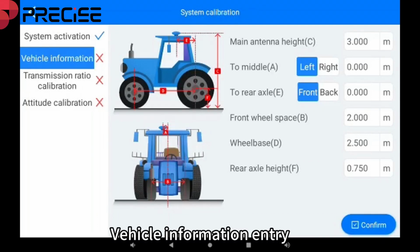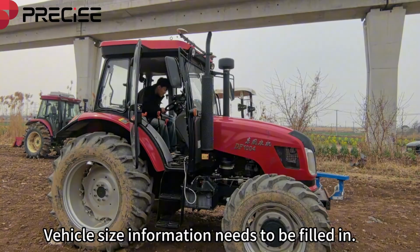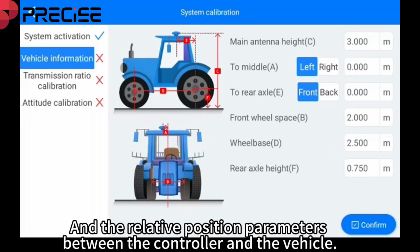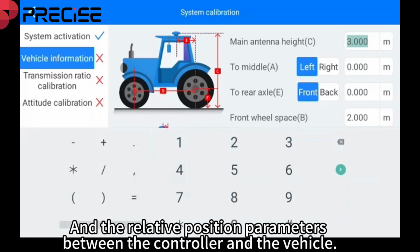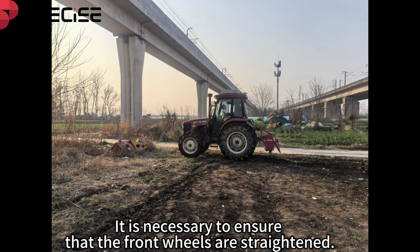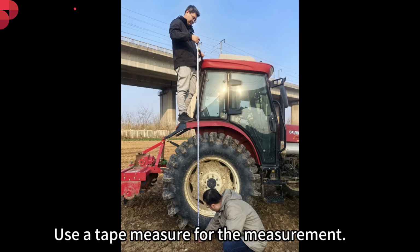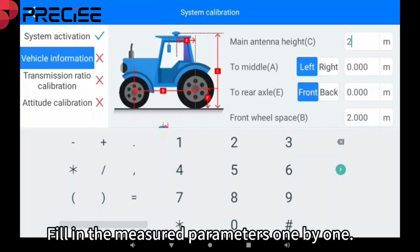Vehicle information entry. Vehicle size information needs to be filled in, and the relative position parameters between the controller and the vehicle. Before measuring the dimensional parameters, it is necessary to ensure that the front wheels are straightened. Use a tape measure for the measurement. The unit is meter. Fill in the measured parameters one by one.